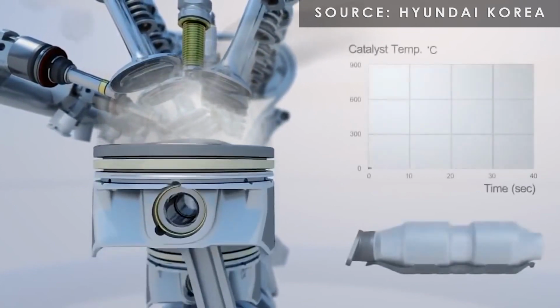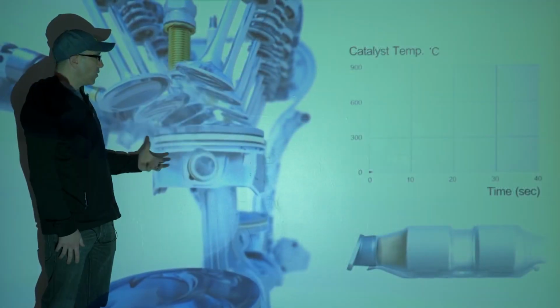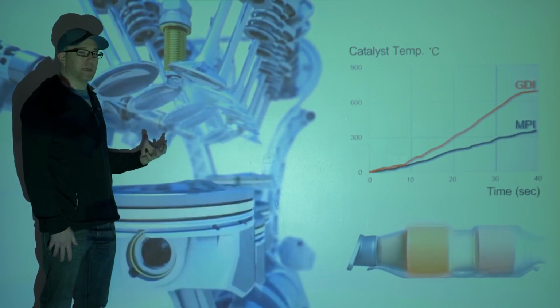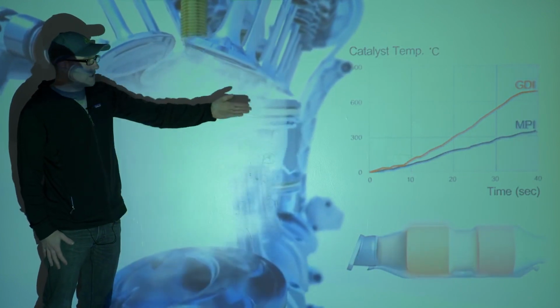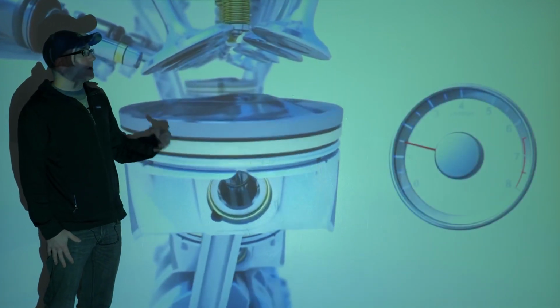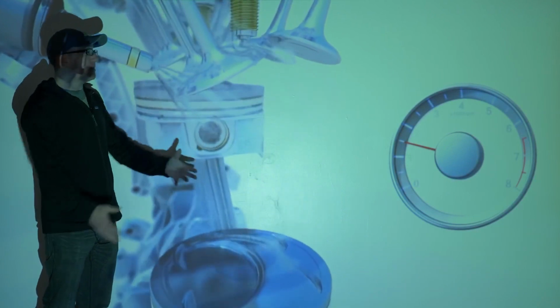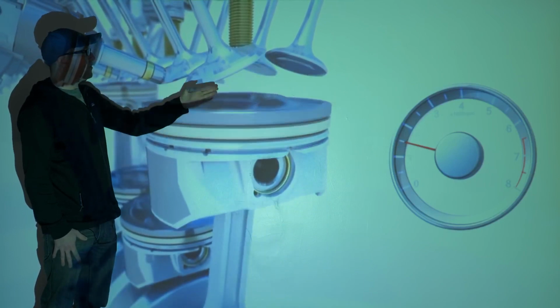Putting a fuel injector inside the cylinder allows them to either create more power or to burn fuel more completely. There's less wasted. They can use less fuel. And obviously, the huge thing here is it can lower temperatures of cylinders. It can create more power and torque. And alternatively, they can change the modes by changing the way that the valves are operated.